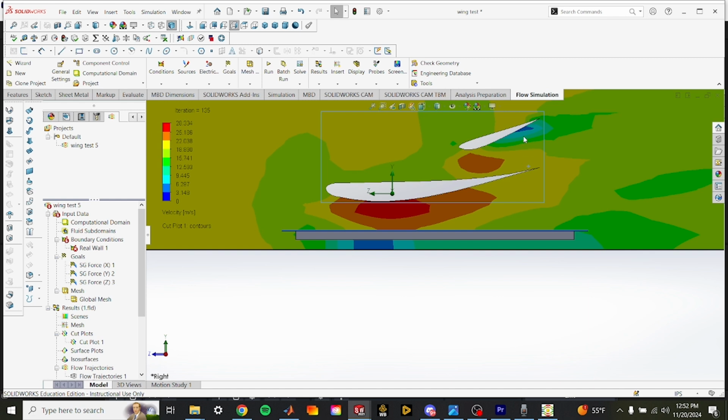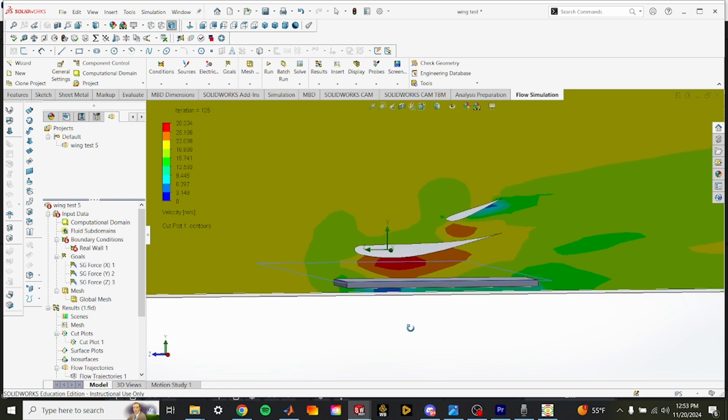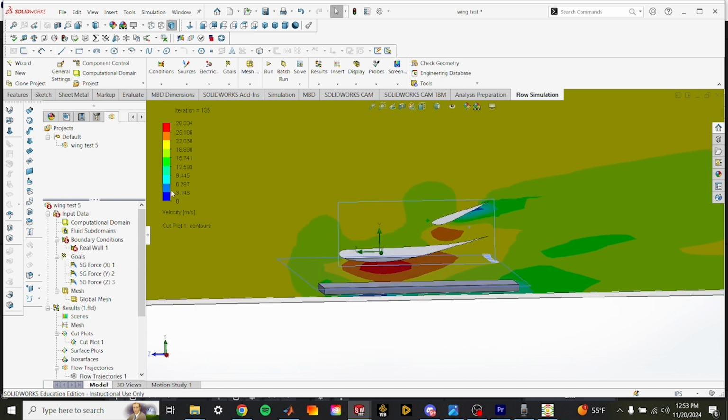The other thing you can see is that the flow is sort of stalling out in the rear of this second element, because it's coming all the way down to 0, and then we're just getting no flow. So we'll either want to make this progression a little more curved so that the air can more easily hold on, or we'll just make this element a little less steep so that the air is not stalling out here. So this is sort of what I would get away from a cut plot, and then I would go in and make these changes accordingly.